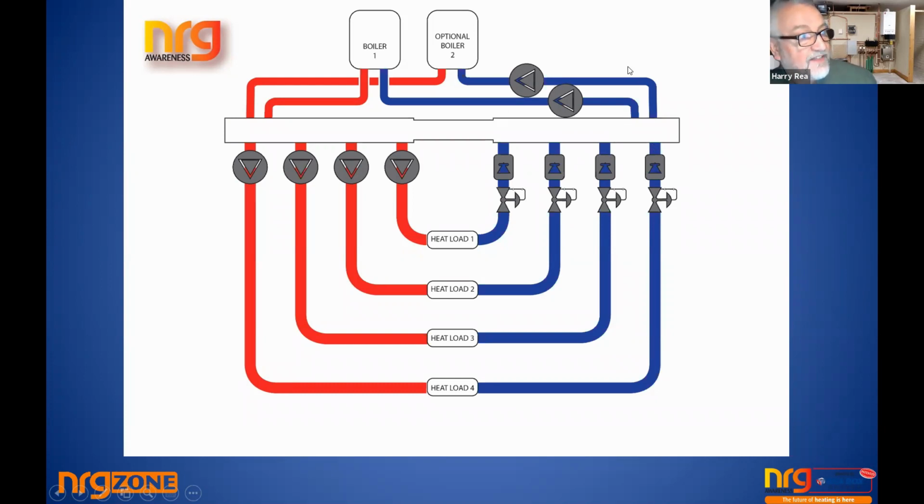So when, say, the common boiler, if there's one boiler or two boilers or three boilers on, their job is to heat the header, and the zones then come back around. But again, we have the same scenario. The header must be able to deliver all the water across, and also the returns, or each zone must take the correct amount, because there's a golden rule. You can't take out more than you put in. So if you're putting in, let's say, 50 kilowatts of heat or a certain amount of liters of water in the boilers, you can't take out 60 out of the zone.